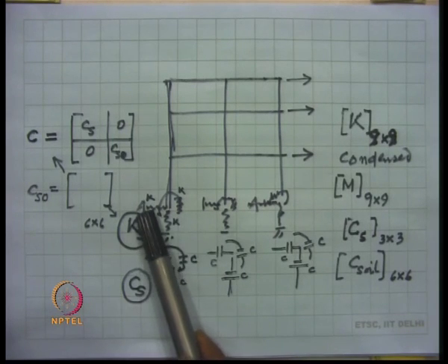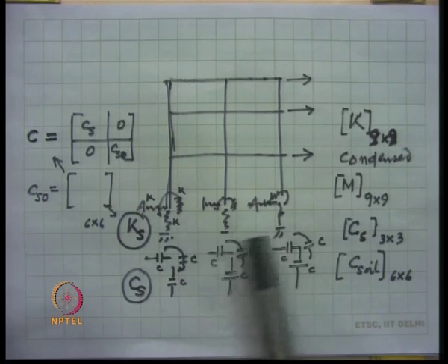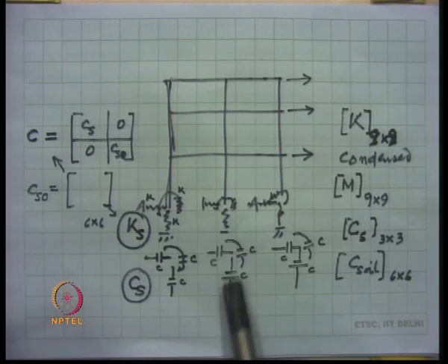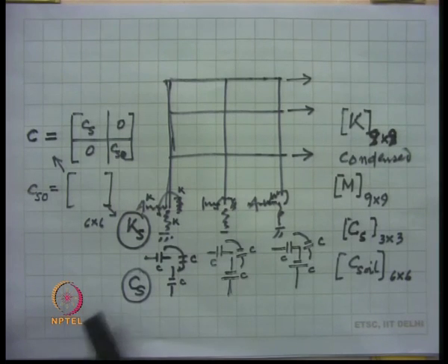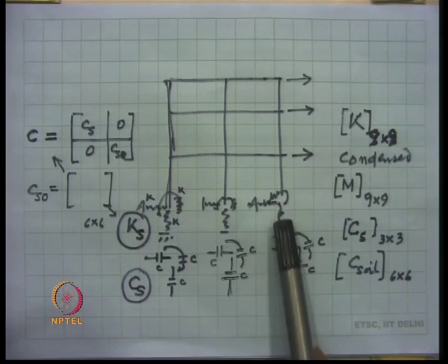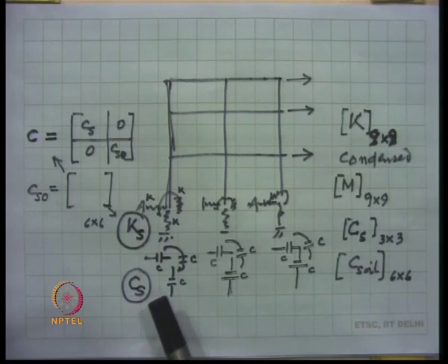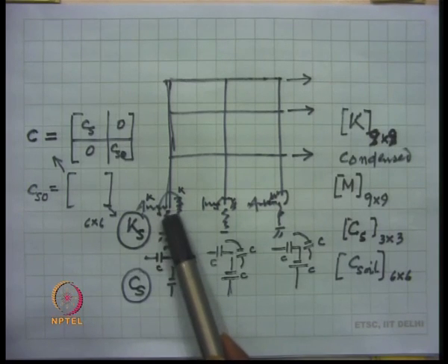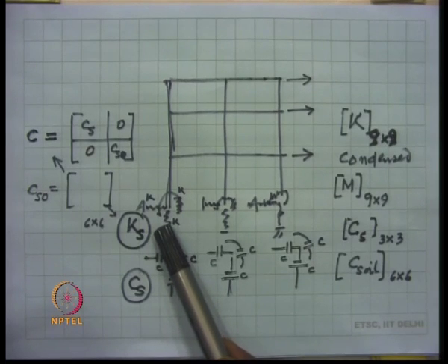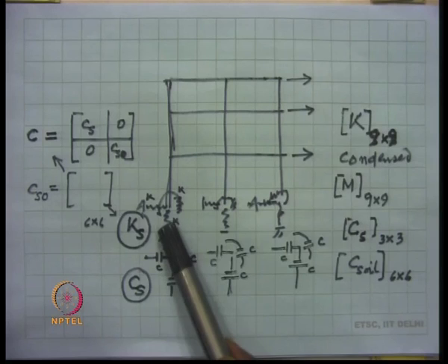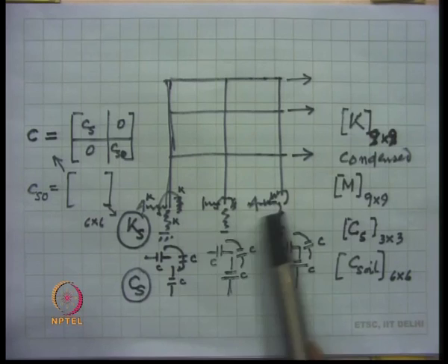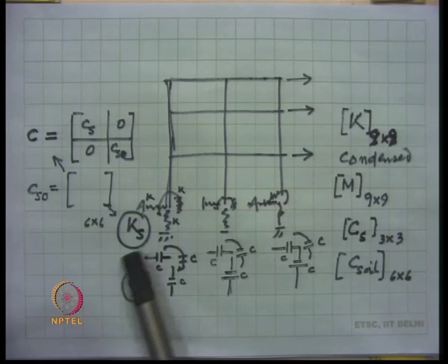At the supports, the springs indicate the soil stiffness and the dashpots indicate the soil damping. Generally, the vertical spring stiffnesses are made very high, so that effectively one can assume that the base cannot go down, that is, the base degree of freedom in the vertical direction is locked. We only permit the lateral movement of the bases.